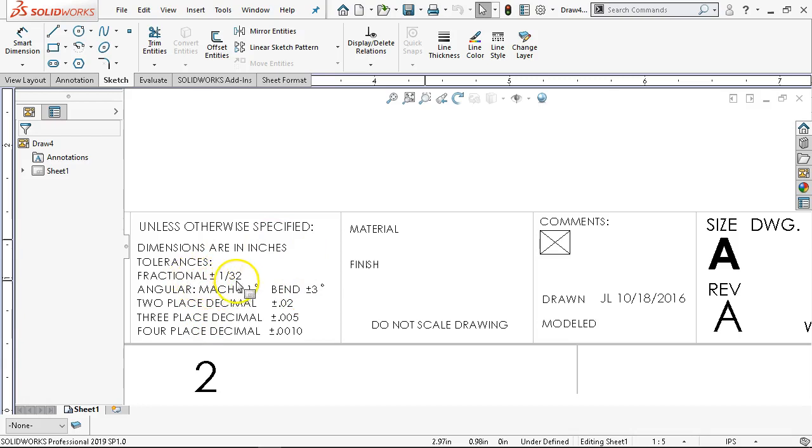And then I mentioned the fractional. Are we really running around with tape measures and only able to measure to a 1/16 of an inch? Well, it should still be pretty close to measuring plus or minus 32nd. But do I go get a scale? Do I go get a rule? And move away from the tape measure side of it. So within the industry, we're going to have commonly accepted tolerances. These should be things that jump out at you.